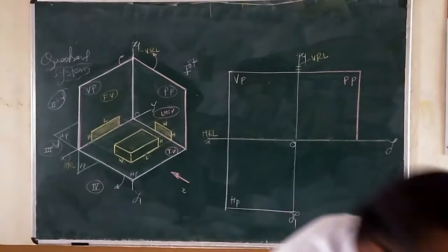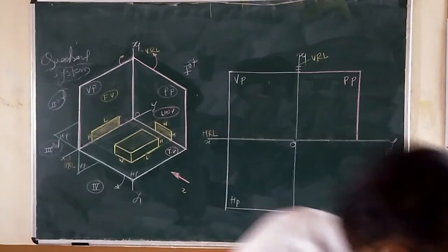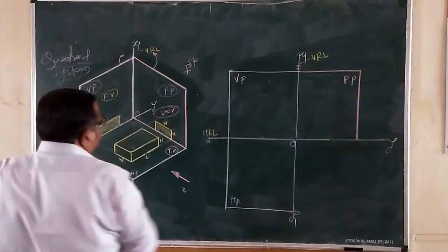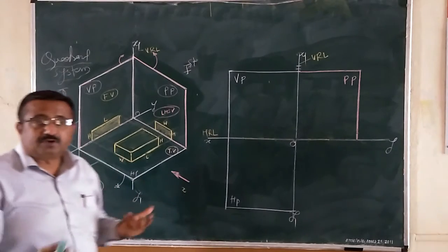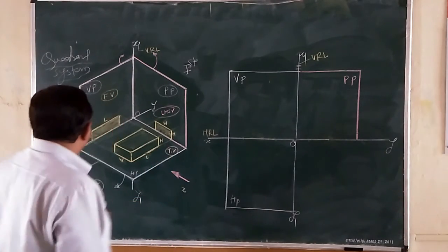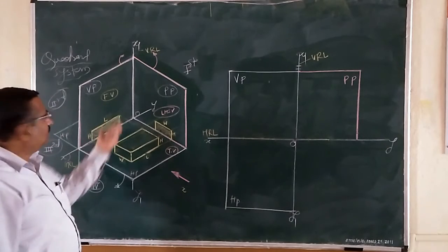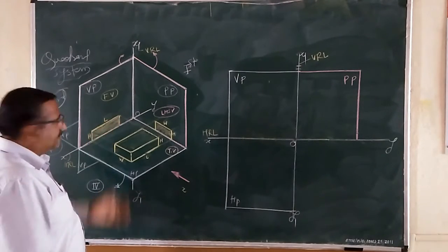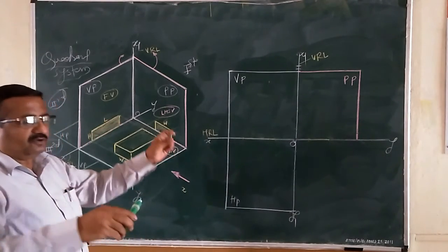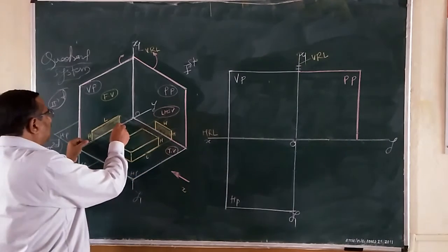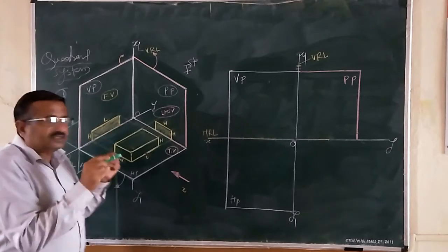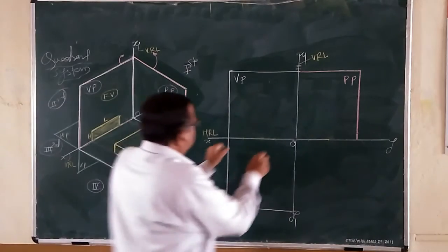Now you just have to pick and place those views, whatever you have got here. 2Ds. This is orthographic projection. So naturally it is the conversion of a 3-dimensional object into 2-dimensional, 3 number of views. So the front view image is here, that we have got. L by H are the prime parameters. Now just by compass only you have to complete that activity. Now, either by scale or by compass, pick this length and get it here.